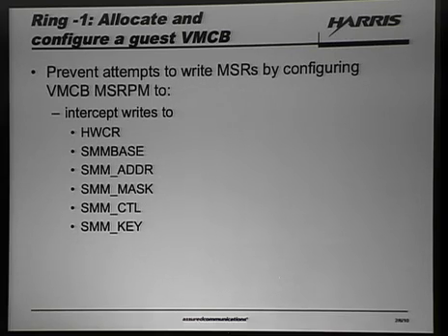The other thing too is that since we've set SM lock to 0, we need to make sure that any of our guests don't attempt to move where SMRAM actually is in the system. Like you could just put SMRAM somewhere in DRAM. So we need to make sure that they don't try to install their own handler somewhere off on the side. That means controlling SM base, SM addr, SM mask, and anything in terms of SM control or even SM key. Because when SMM lock is 0, if you write to SM key, you've now reset the password. So potentially, if we had to lock it again, we couldn't unlock it.